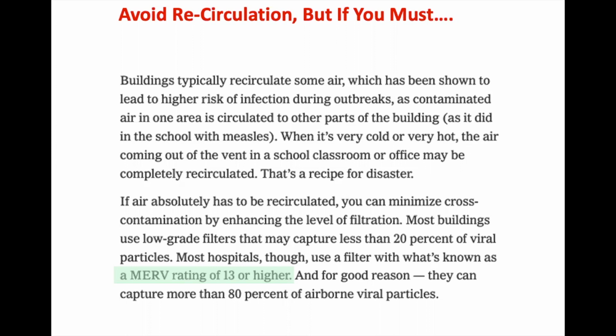If you had been using a dedicated outdoor air system with very high efficiency heat recovery, all that goes away. And in another later session, we'll bring it back again. I've been talking a lot about this over the last number of years, retrofitting buildings to put in very high efficiency heat recovery ventilation to do a dedicated outdoor air system, and then putting in heat pumps, and you save an average in offices, we're saving an average of about 70% of the energy to do that retrofit. And now we've met our ventilation and filter and more outside air that we're after, and we can pay for that by doing huge energy savings.